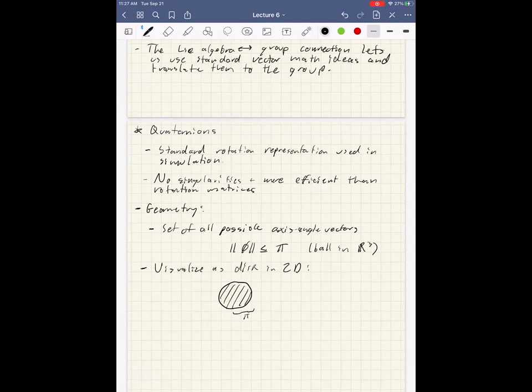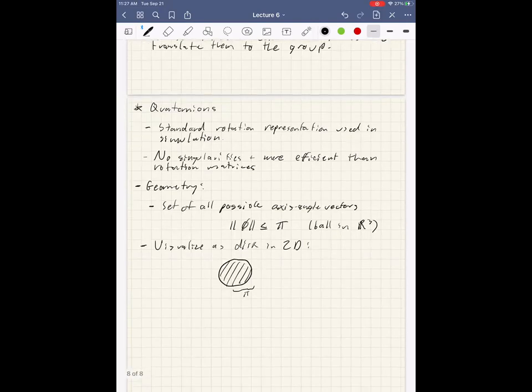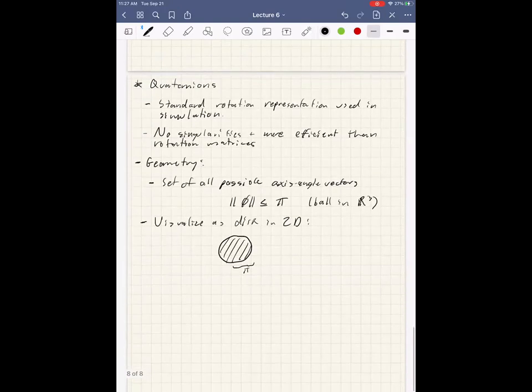There's this kind of weird discontinuity wraparound situation. Basically, if I'm at pi plus epsilon here, I end up at minus pi on the other side. I'm talking about just trying to simulate this, represent it. And that discontinuous jump is called a kinematic singularity. It's bad. It does bad things to us. It means we can't just write down nice, clean ODEs, and I have to write this down as a hybrid system or do other weird stuff that I don't like.